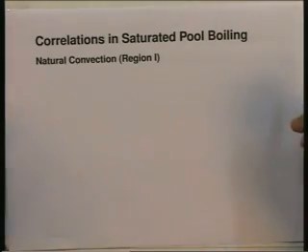By saturated pool boiling, I mean that we have of course a pool of liquid, and in that pool the liquid, whatever it is, is at a certain pressure and at the saturation temperature corresponding to that particular pressure. So, that is what we call a saturated pool. It is at a particular pressure and it is also at the particular saturation temperature corresponding to that pressure.